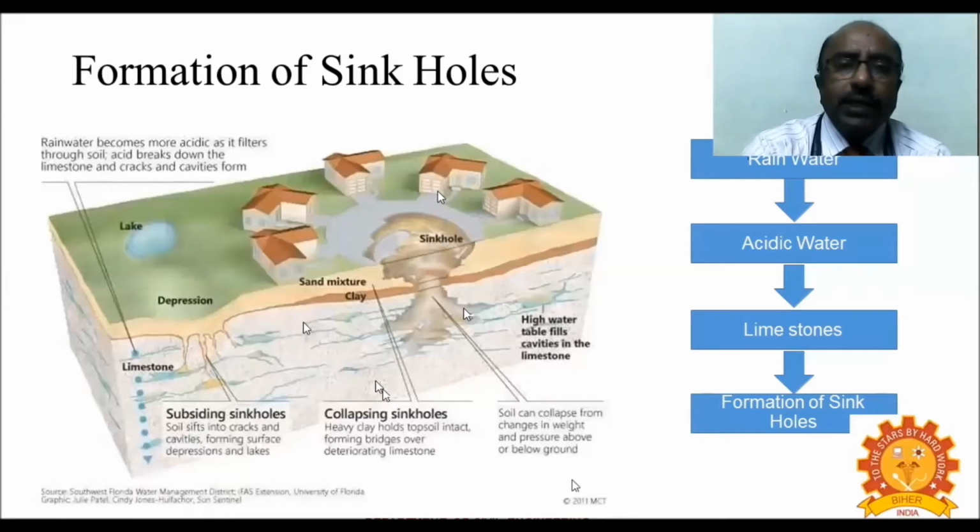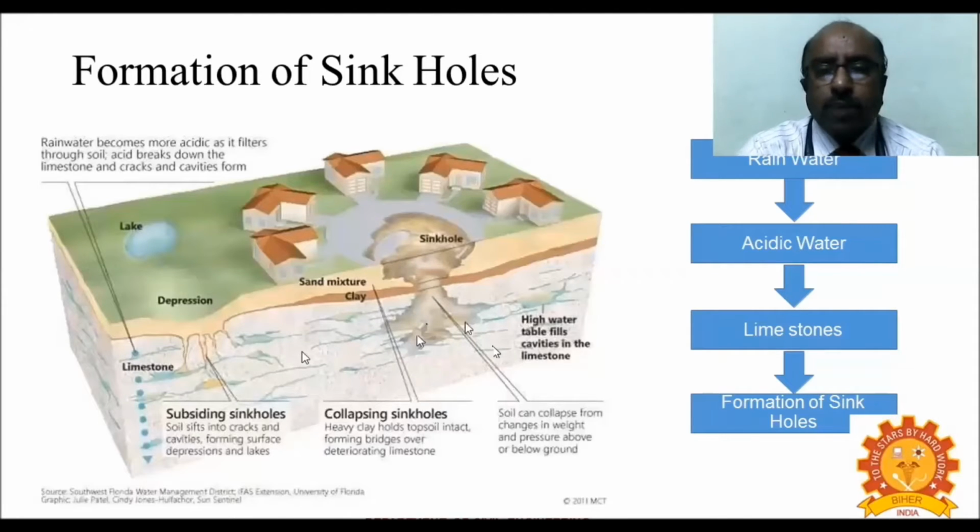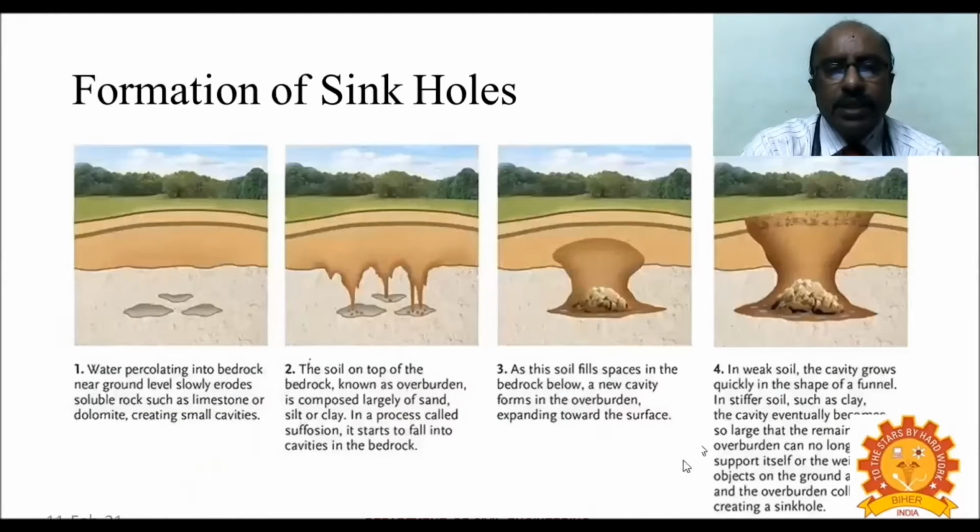So initially we will not know the ground; yes, it is good, yes, we can construct. But later on, because of the acidic water, because of the acid rain, the leaching takes place and everything below is washed away or there is lateral movement, and one day we suddenly see a sinkhole. So this has to be avoided.